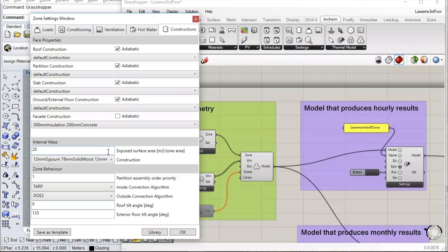This is to describe the net surface area of things like internal walls, and almost an assumption of if all the furniture and every physical object within the zone was made out of this construction material here, which you can select out of your pull-down menu, roughly what would be the net exposed surface area of that equivalent thermal mass, which can be very hairy for anyone, including the most expert engineers, to estimate.